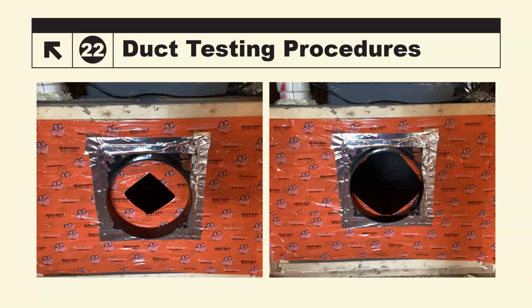The testing of the ducts is only a test of pressure differential from the fan to the probe. So if you have to turn the fan speed higher to overcome a smaller hole that you have here, you're either overstating or understating the pressure differential of the fan and the test results. So you're getting inaccurate test results, in my opinion. If I was QAing someone that did this, the first thing I would do is cut the hole to the right size, as you see on the right-hand side. I would run my test and record the difference from what they got.